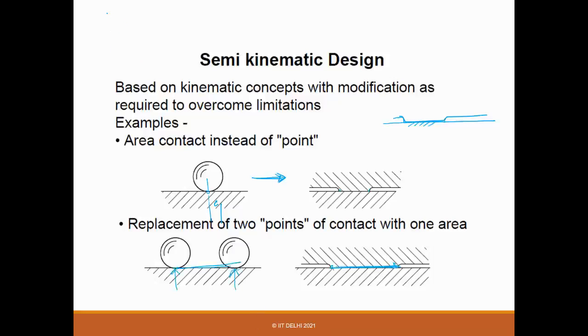You don't design something like this, with one component on the other, where you know it should sit like this. You never do that, because of the machining effort: the flatness and surface quality you have to maintain from here to here. What you do is make a groove. Then you know that the important points are only these two.